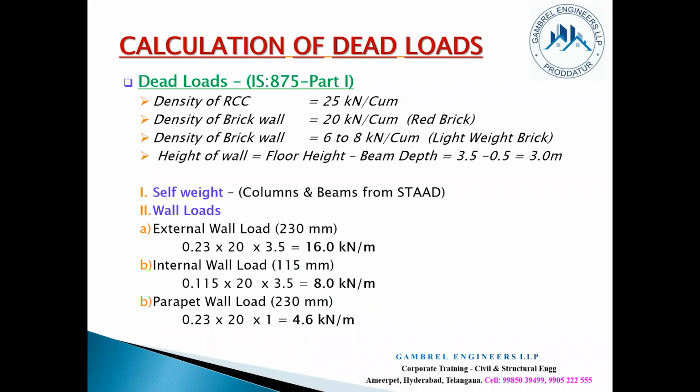Now let's recollect what we have discussed. We discussed what a structure is, what analysis is, what design is, and we discussed column. We studied the architectural details like the building type, building size, plot size, slab size, setbacks, and then area conversion into different unit systems, cent, square yards, square meters. When that is discussed, the next step is to focus on the column position and column orientation. We discussed column position. We'll discuss column orientation in the next 5 minutes.